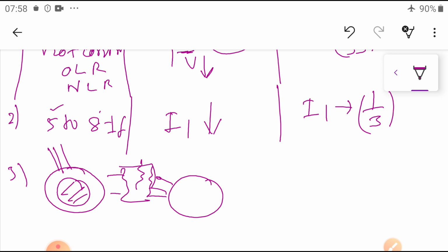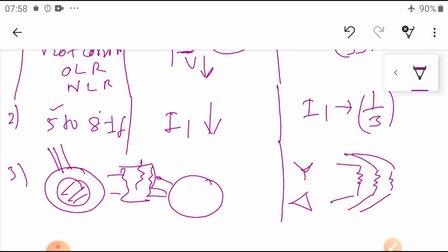In the star delta case, 6 wires we are going to connect. So this winding, this winding, this winding. We have to take out S1, S2 and the other terminals. We have to connect the star initially, and after that connect the delta. So that arrangement is required. That means 6 wires are taken out from the stator, 3 wires and another 3 wires. Okay, so that is another factor.